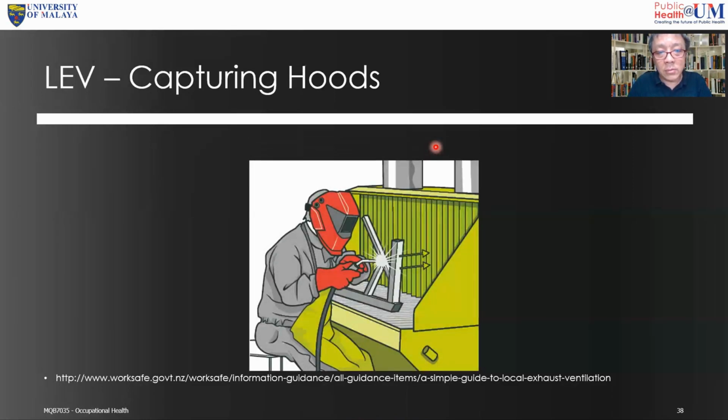And this is an example of unidirectional flow that we can see. All right. So there's the suction, and then the fresh air is blown from behind. So the fresh air will be able to cool the worker down, and the contaminated air will be sucked in front, so that the worker would not be affected by the contaminated air. So what is the issue when you do welding? You get fume, and that is where you need to suck the fume. So you must design the LEV based on the hazard itself, whether it can actually suck the fume or whether it can filter the fume. Okay.